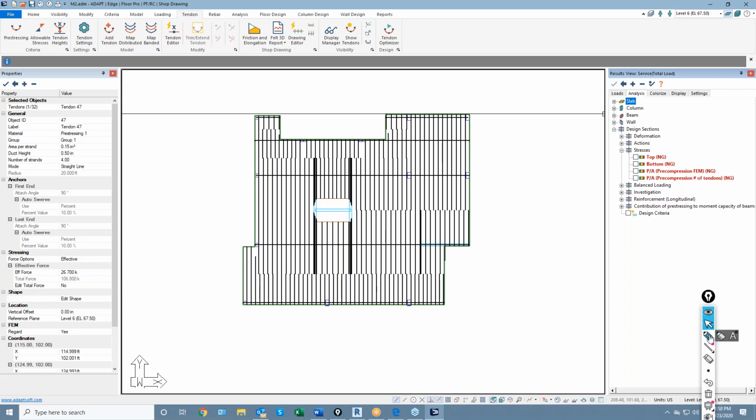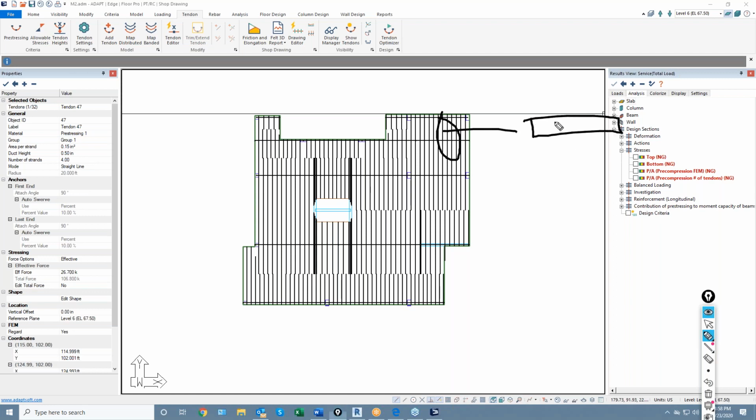We essentially took the design cut, which has some area of the concrete, and we take the axial force that's integrated as a resultant force. Let's say this is called N. That force at the CG of the cut due to the in-plane action is used, and we take N over A sub C to get the FEM result.